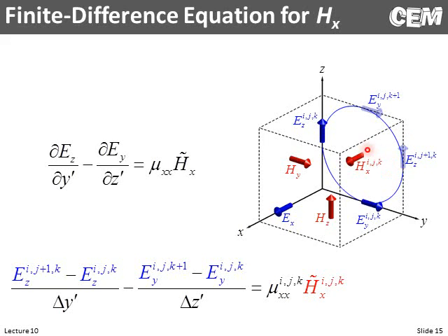That way this h sub x is right at the midpoint between them, and we can use a central finite difference to approximate the derivative. Okay, slope. So it's going to be this electric field minus this electric field divided by the spacing. So the quick way I'll word that is the electric field from the next cell minus the electric field from the same cell as the h sub x we're talking about, divided by the spacing, delta x. So here is our finite difference approximation.